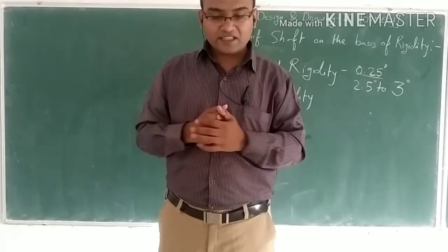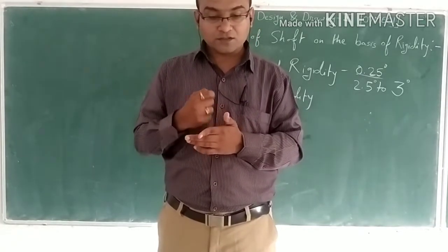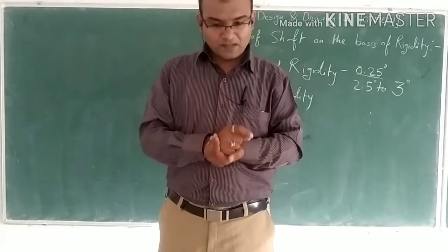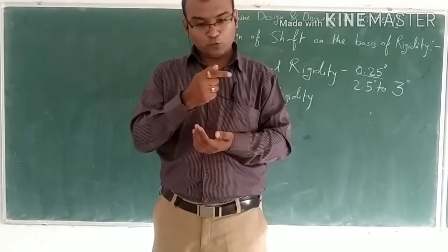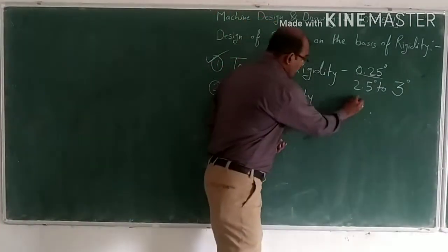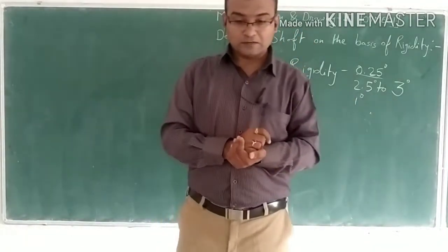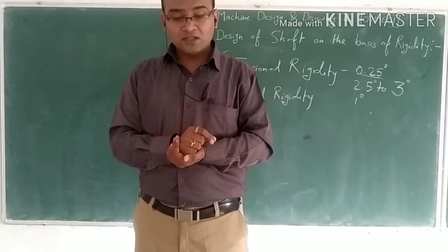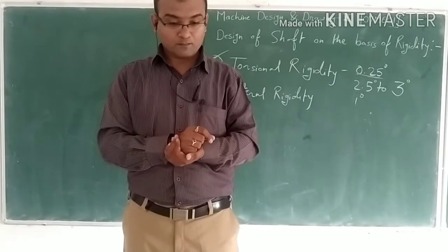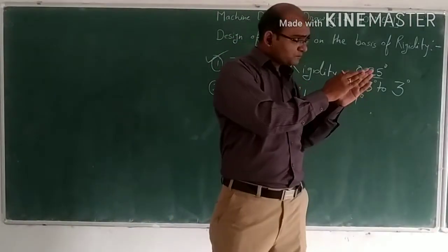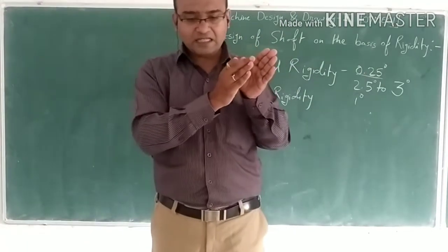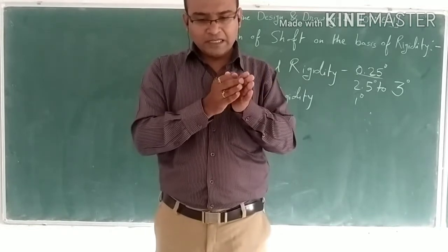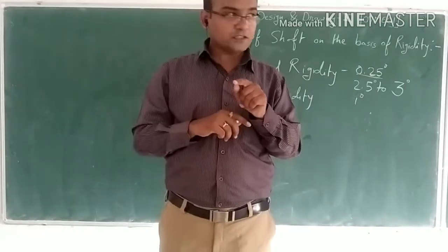The widely used deflection for the shaft is limited to 1 degree in a length equal to 20 times the diameter of the shaft.